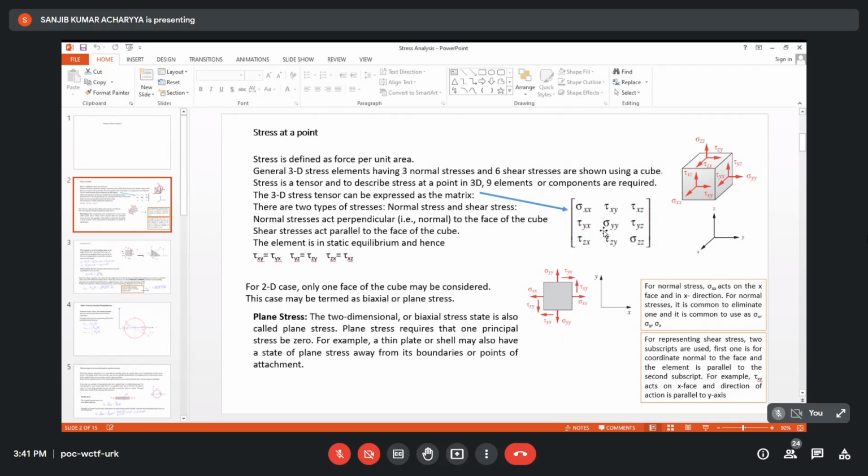Okay, somebody can tell, sir, you are ignoring the shear stress due to bending. No, I am not ignoring. You know that there is a shear stress distribution, no? In case of bending load, which is maximum at the center, minimum at the surface. I can ignore it only because in magnitude it is very low. If somebody is interested and wants to make it more accurate, he is always allowed to include that effect of shear stress in the member. I have no objection.